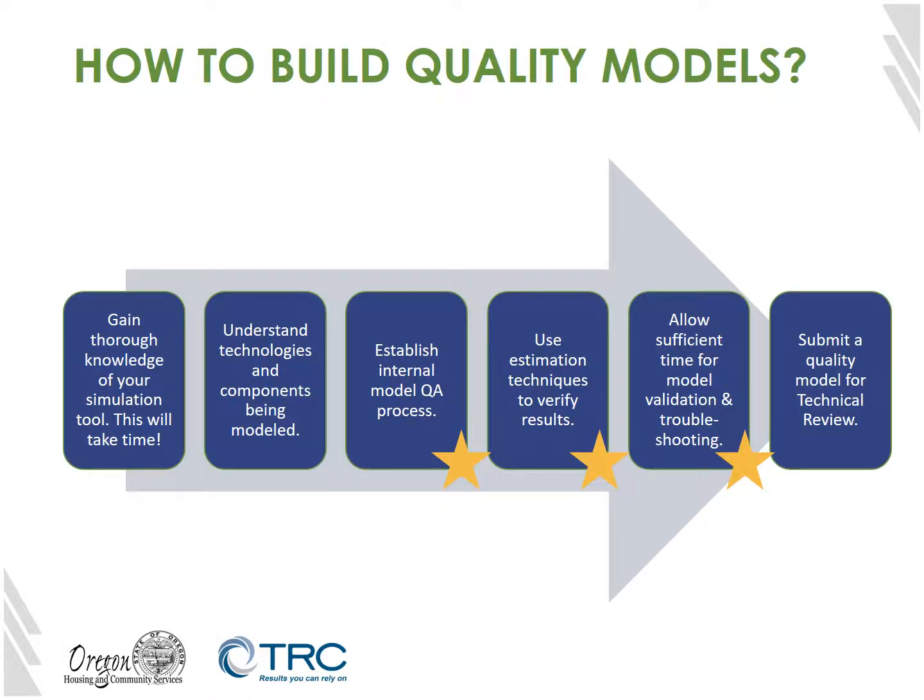This shows the important steps on how to build quality energy models for submittal in the Multifamily Energy Program. First, you need to gain thorough knowledge of the simulation tool. Training courses are available for many energy modeling softwares such as eQuest and REMrate, both online and in person. In addition to the simulation software, you also want to develop a firm understanding of the technologies and components being modeled. Some software tools have complex inputs, and a thorough understanding of building components will help in the modeling process.